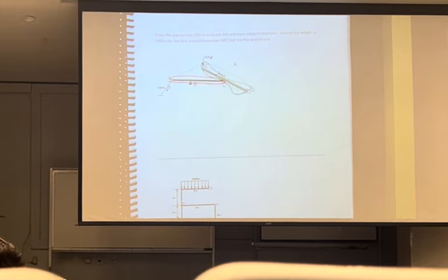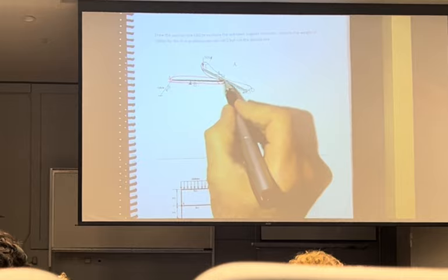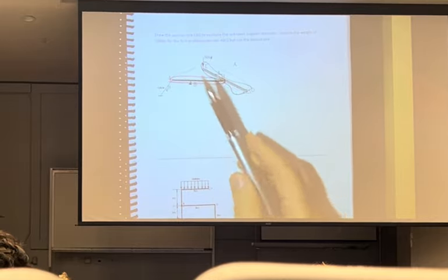That would be a little better, because now I generate how many equations? 6. 3 per free body diagram. That makes life much easier for me. And how many unknowns would I generate? 6. Because you're going to generate this unknown between the 2.